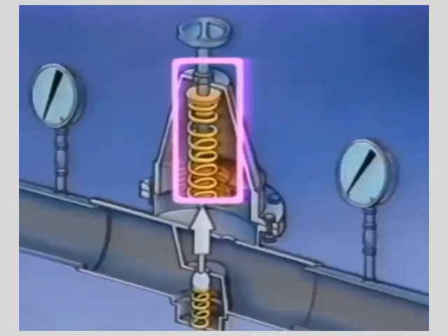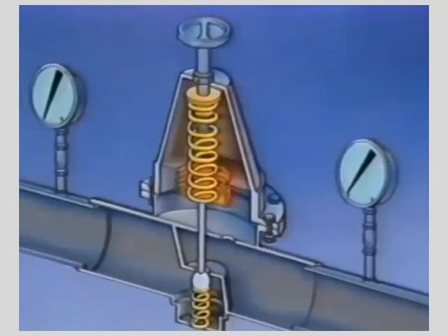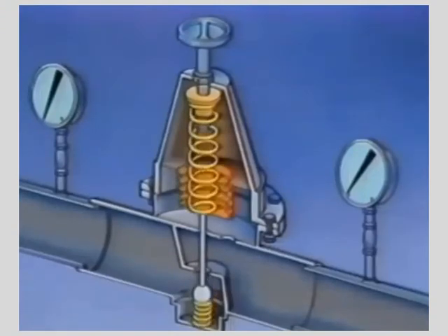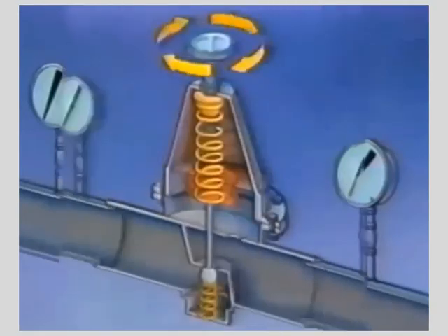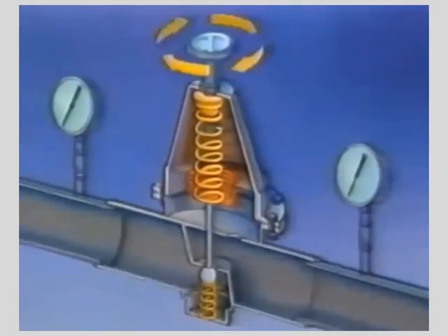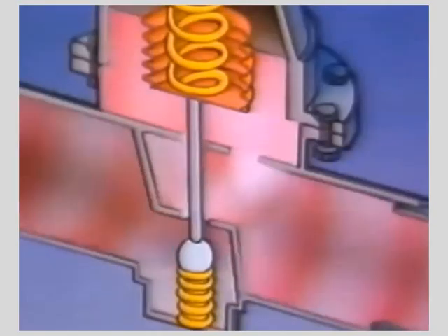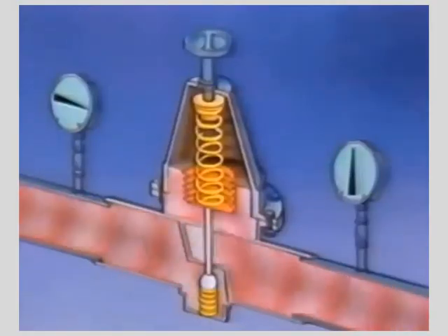If downstream pressure is less than spring pressure, the diaphragm will flex downward, forcing the stem downward and moving the disc off the seat, allowing increased flow through the valve. The outlet pressure can be adjusted by compressing the spring to maintain downstream pressure higher or decompressing the spring to maintain downstream pressure lower. The valve will typically find some throttle position that maintains pressure for a particular load.